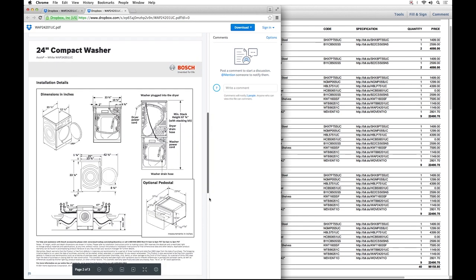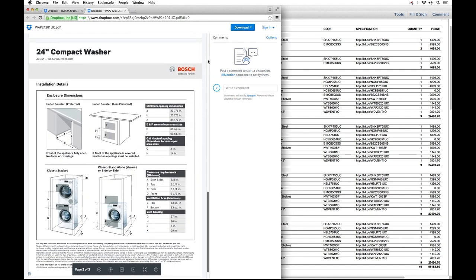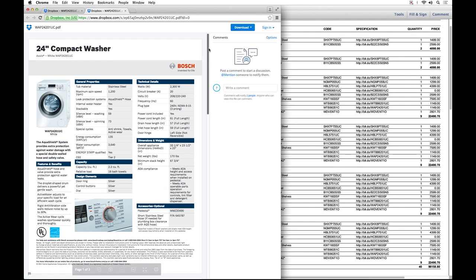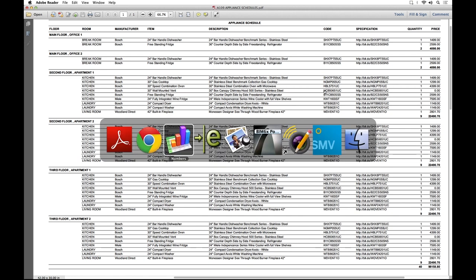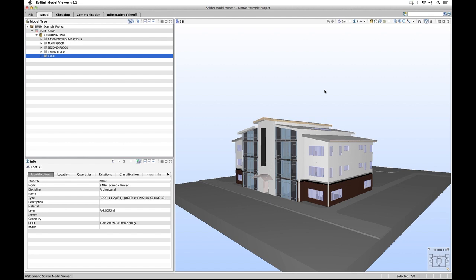The reason why we locate it on our Dropbox is so that we always know the path of that information. If the manufacturer were to move it, we'd have to go back in and relink it here. So we put that information on our Dropbox folder, which is pretty powerful. Again, this is all free information coming straight from the model and the power of a good pre-link template.